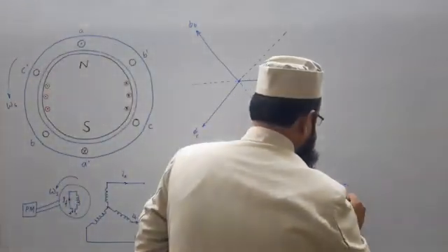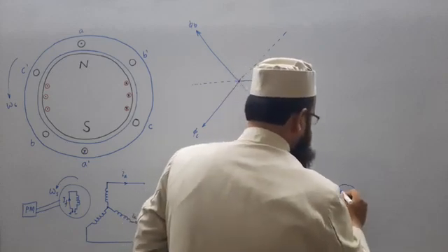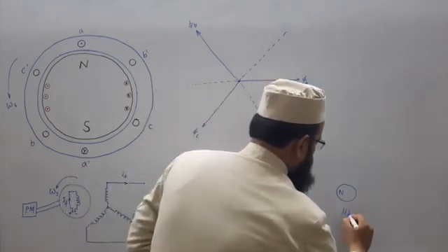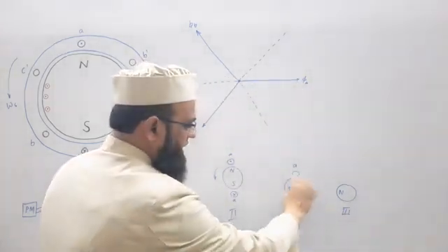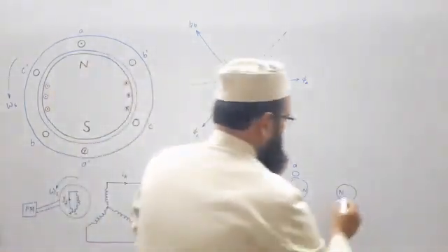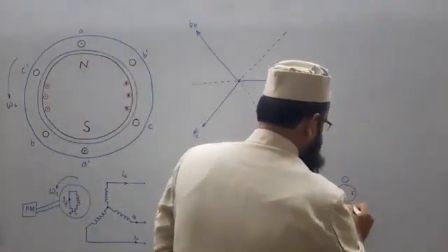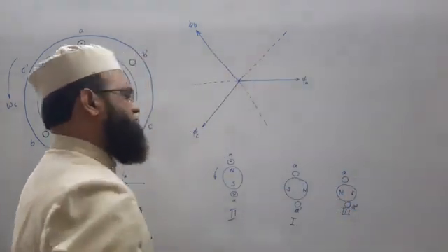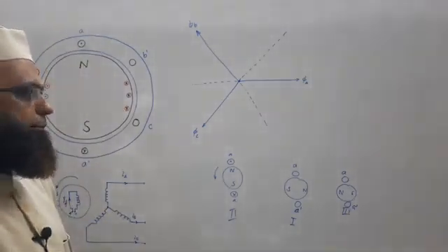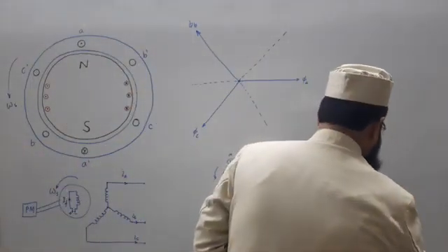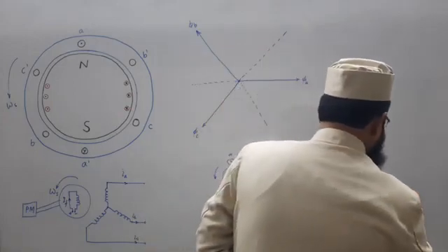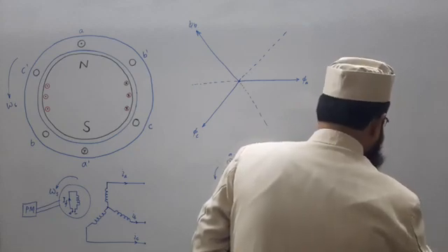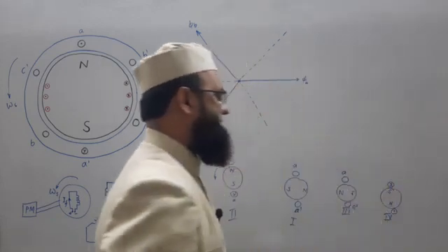And again, let us take some more cases. So after this, let us take case 1. This is case 1 basically, this is 2, and now take 3, because it will start from 1, then rotate and attain this position 2, then attain next 3. So here also we can see that A dash, this is having 0, right? And let us take the 4th case, when the rotor is having S here, N here, 4th case. So this will be cross and this will be dot as discussed earlier.